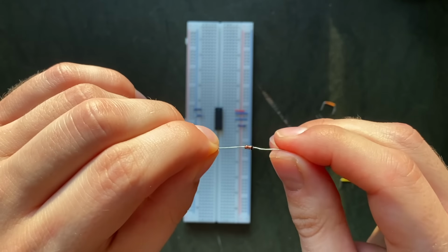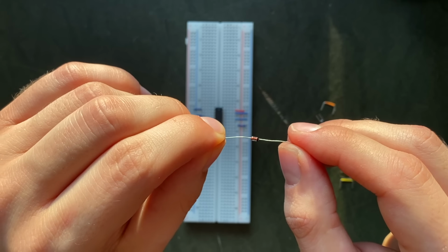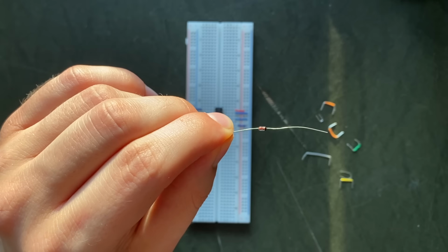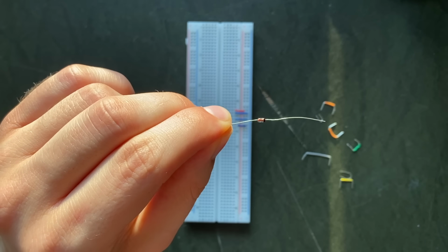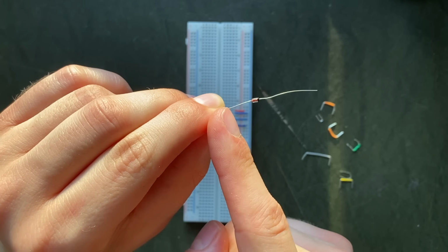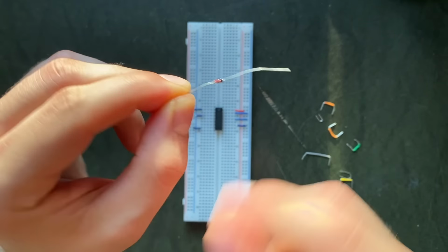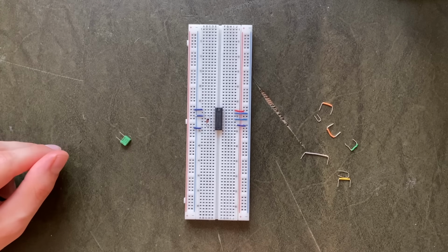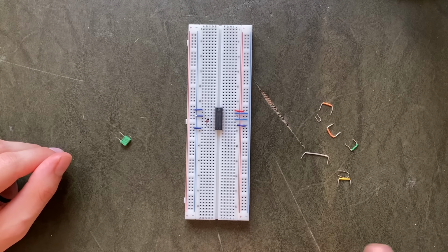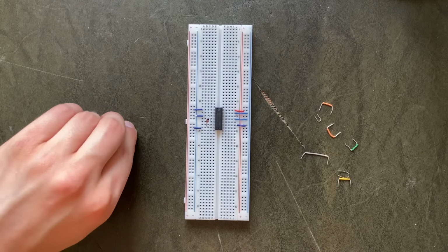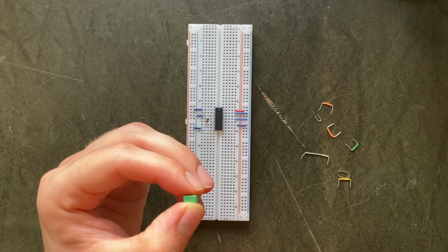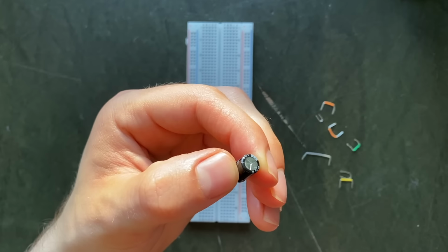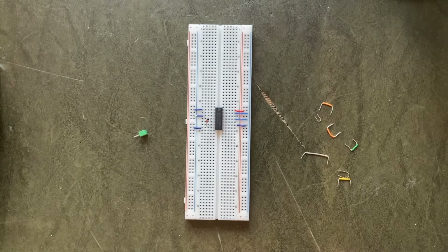Orientation is important here. If you look at it closely, you'll notice this thick black stripe on one side of it. This represents the line in the diode symbol, meaning that current can only flow from here to here. For the capacitor, the orientation doesn't matter, but beware, that's not true for every type. I'm using a foil capacitor here, which is non-polarized. Electrolytic ones, on the other hand, are polarized. Make sure to keep this in mind.